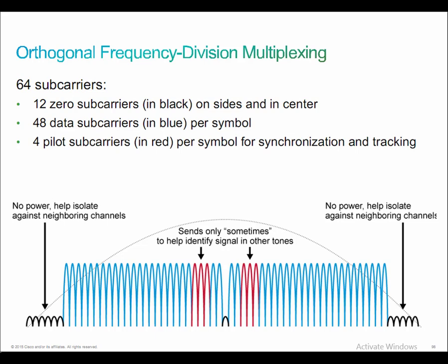We also have a narrowband frequency in the middle that's marked, that allows us to mark the center band, the center of the carrier, because the idea is that as you move to the center frequencies, you're going to have higher fidelity and less interference and so on. All right. So just to reiterate, you have 64 subcarriers. Only 48 of these subcarriers are actually used to carry data. That would be represented by the blue ones here on the screen, and the red ones as well.